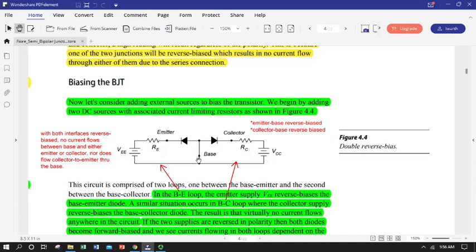We can push charge up and down those energy hills represented by the PN junctions, and of course the way we push charge up and down a fixed voltage in our semiconductors is with an applied voltage from the outside of the device. We did that like crazy with diodes and got them to open, or we reverse biased them and kept charges from running up or down the hill as we wanted. So we can do the same thing here. A PN junction is a PN junction.